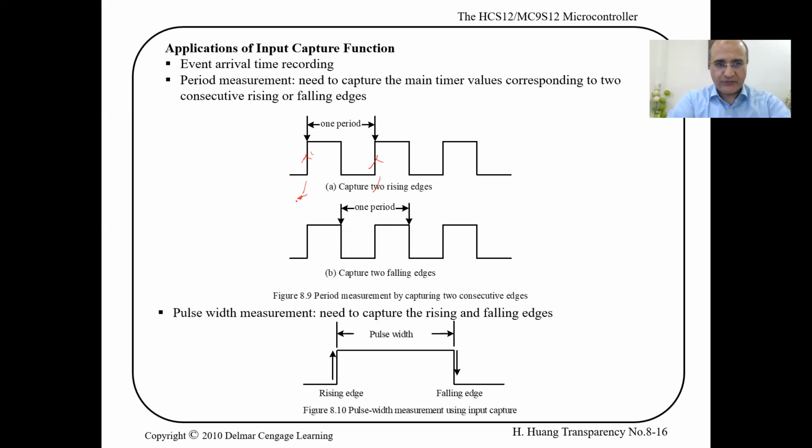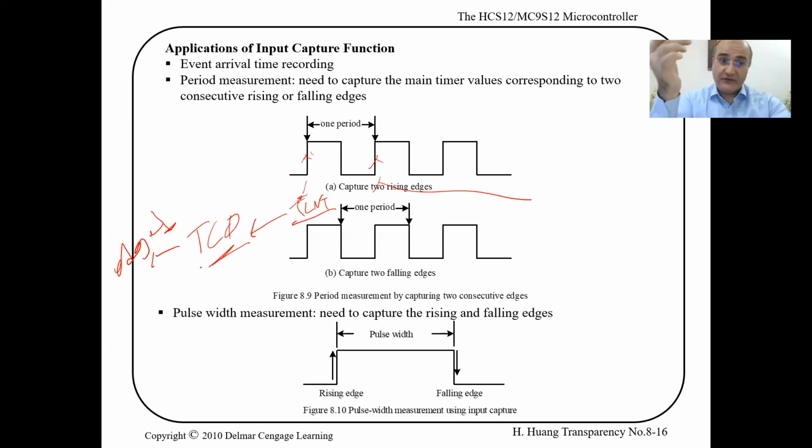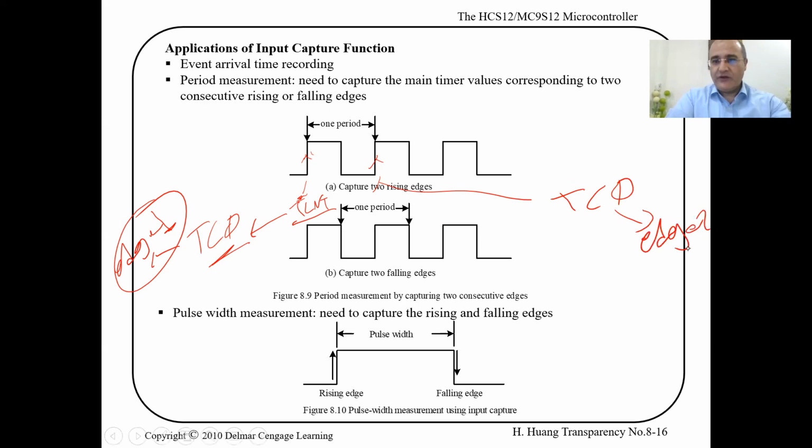You can go subtract the timer value when it is captured here, if we are at channel 0, in TC0, then store it somewhere called edge 1, right? When an interrupt happens, or you keep waiting for the flag to raise and go capture it. And when it happens again, go save it at edge 2. Then you have two values, subtract them.